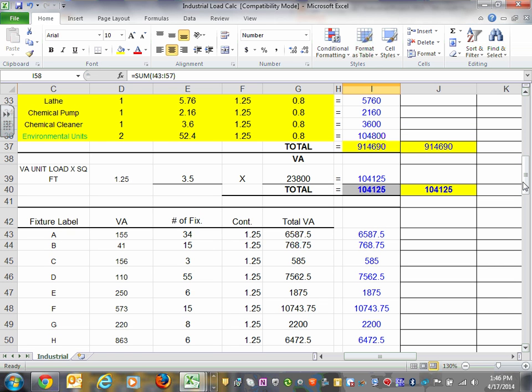So what would you do? In 2014, guys, the NEC code book allows some changes. If you can prove that this is the load and monitor it so you can't overload your circuits, you can use the actual load to size your circuits. Another way is, that 3.5 is an assumption, assuming it's across the board for a commercial building. You can go there and treat the support areas and try to get lower values by treating it area per area. You can get lower.